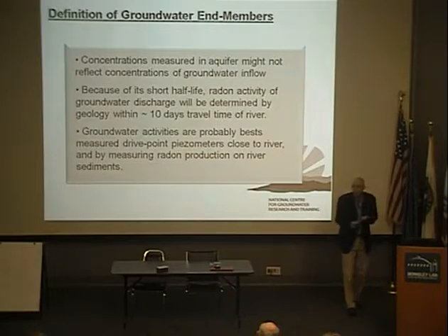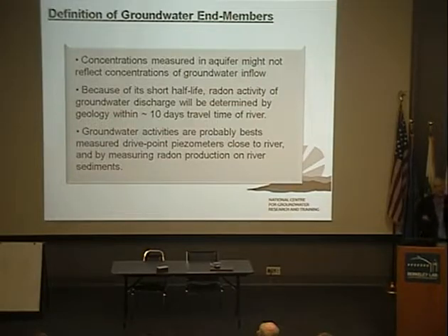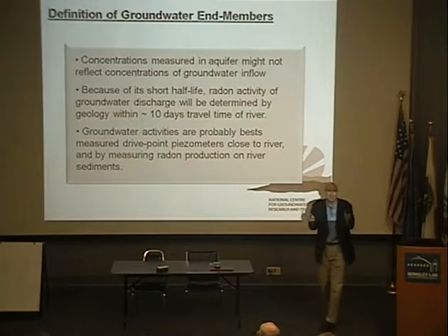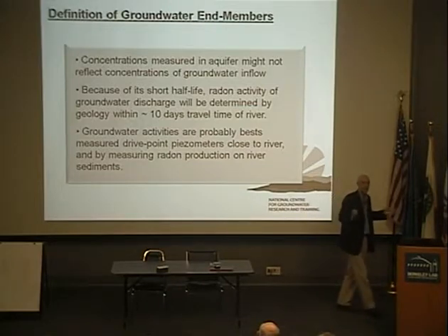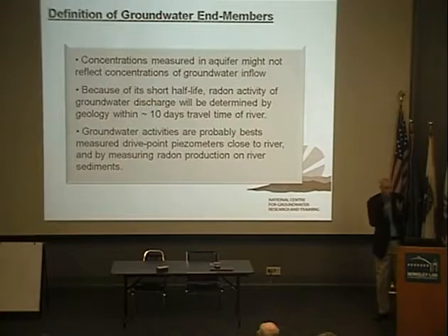When we're using radon, radon has a half-life of 3.8 days. So the concentration in groundwater discharge is determined by the geology within about the last 10 days of travel, which is probably distances of metres to tens of metres. So there's a caution in using a bore a kilometre away to tell you the end member. There's a danger there. We'd be better off sampling in just sort of dry points right near the stream to get that end member.